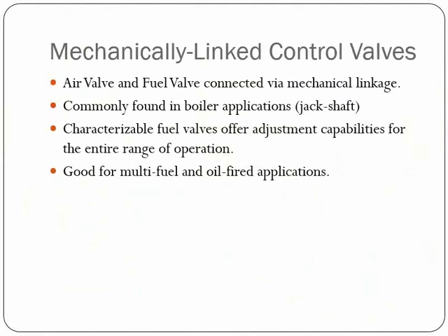of operations. So if we go back to ratio regulators for a minute, the way that those are set up is that you've got your air valve moving up and down, and your gas is essentially fixed to the air valve. But if you wanted to tweak and make micro adjustments along the stroke between low fire and high fire, you don't have that capability with a ratio regulator unless you start adding additional components into the system.